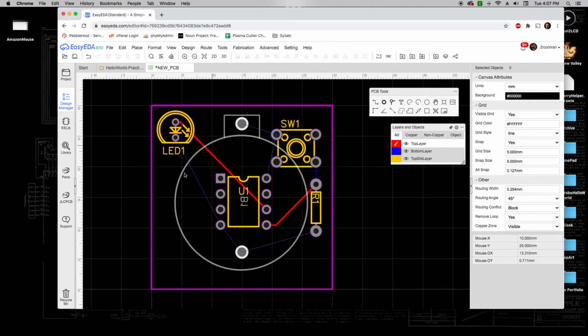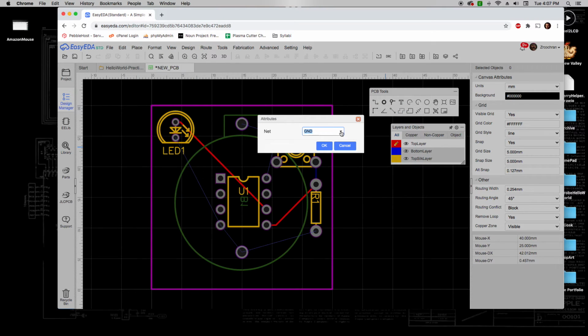I'm going to turn everything into a big copper plane called a power plane, and that's going to automatically connect all of the little power points by just covering the whole top of the board with a piece of copper that's positively charged. So to do that, I'm going to come over to this copper area, and I'm going to choose what I want to fill it up with. So I'm going to say this is power plane, so we'll go to VCC and click OK.